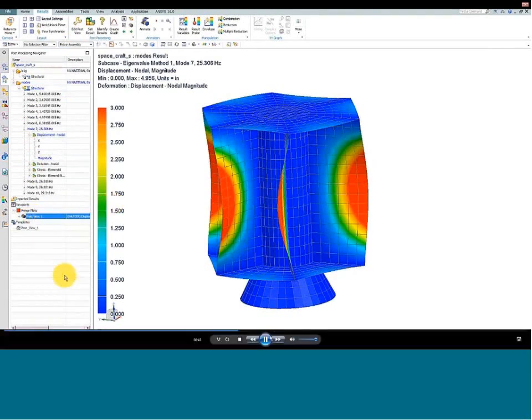And so now that I've done that, now that I've got my settings in place, what I do is I right-click on the post view in this viewports section of the post-processing navigator, and I come down to where it says New Template. And when I click New Template, now you'll notice I have a new entity in this tree down here. So I'm going to rename this and give it a meaningful name. And in this case, I'll call it My Template.